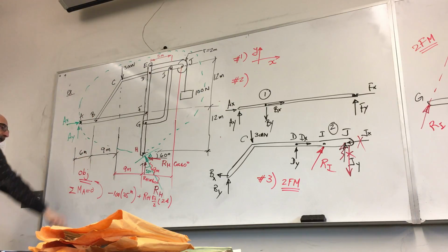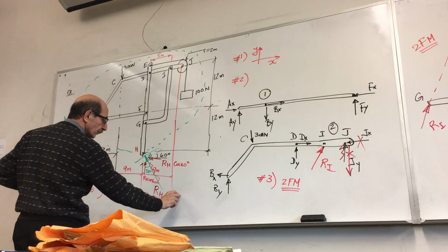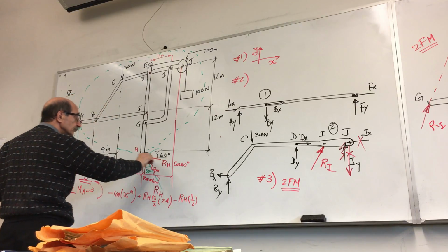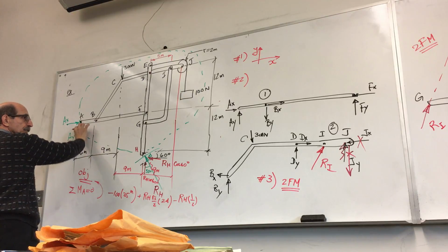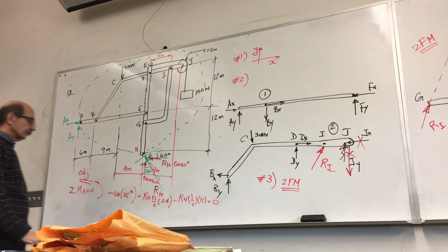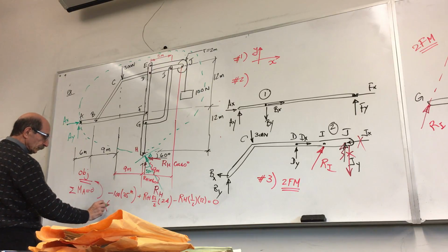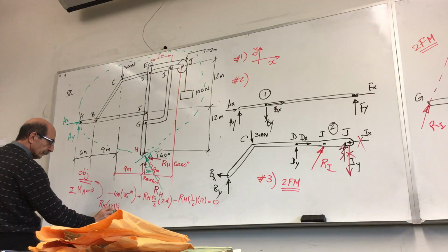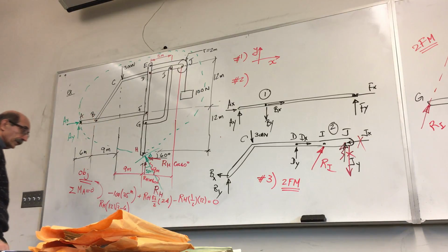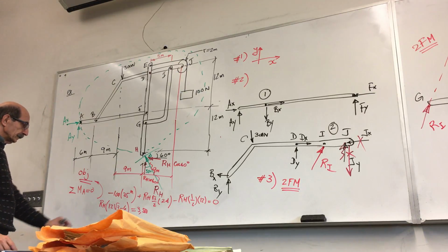This one is, again, clockwise, and it is negative then. So you have negative RH cosine 60, which is 1/2, times this distance. This distance is 12, so times 12 is equal to 0. So I have RH times (12√3 minus 6) is equal to 3,500. So somebody's going to give me RH.